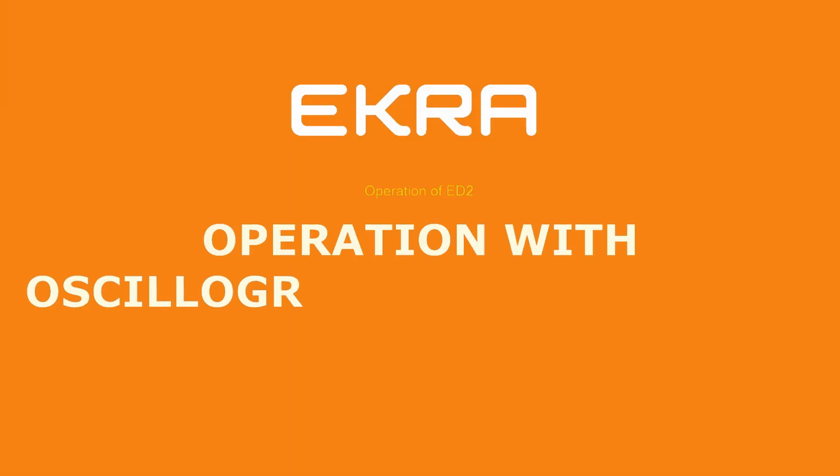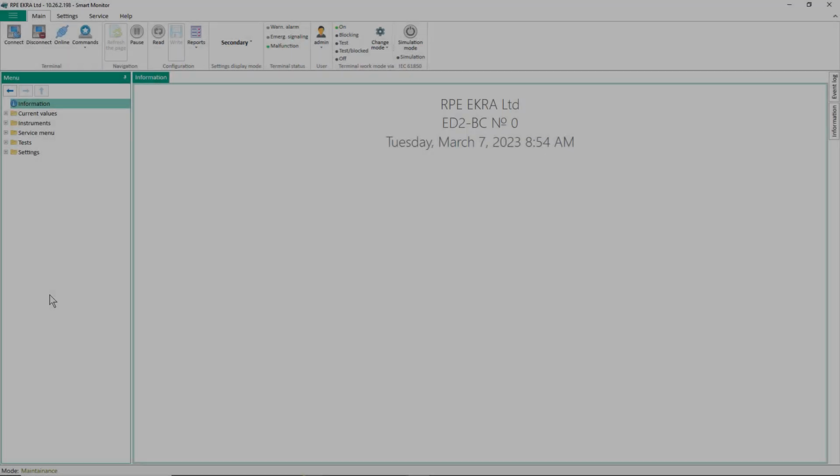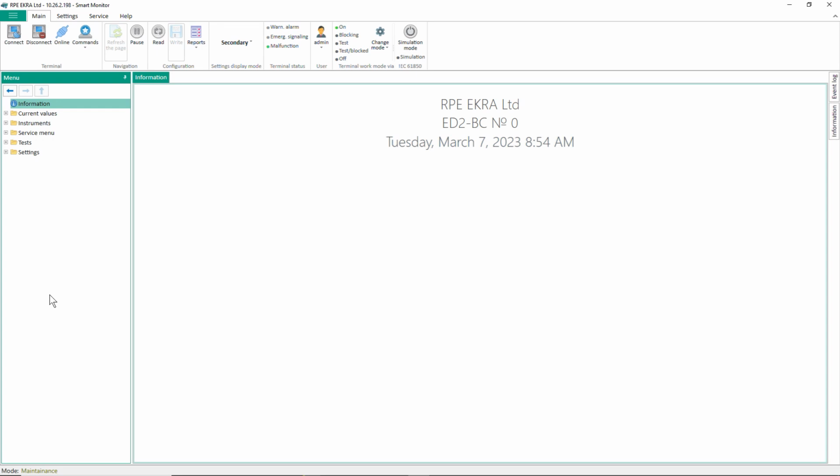In this video tutorial, you will learn how to download and work with oscillograms, also called waveforms or disturbance records, and how to adjust the auto-sending of oscillograms by email and to substation automation system. ED2 series IEDs provide recording of oscillograms with binary and analog signals, transfer oscillograms via the digital channels and quickly download oscillograms to USB flash drive.